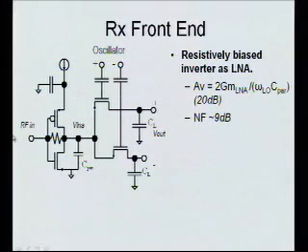Okay, so the idea here is that if there's no signal, then if I get rid of the cap and I just put current into this, I would basically have two VGSs, the VGSN and the VGSP, and this feedback guarantees that. All the cap does is that at low frequencies, that's your voltage drop here. The cap just makes this look like a ground at high frequencies, so that I get the GM from this device and this device. That's all.